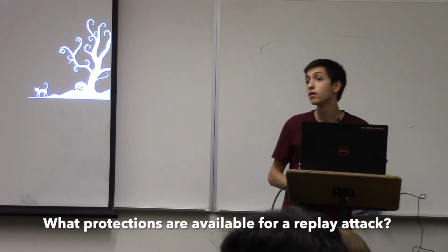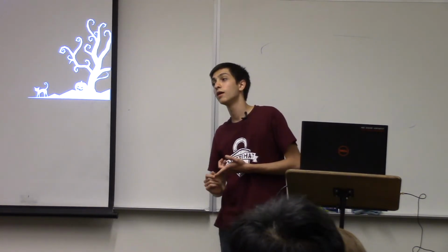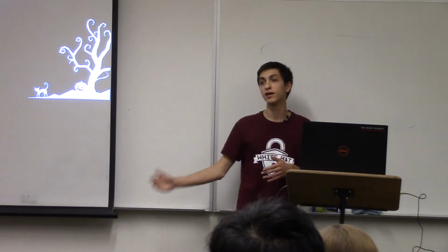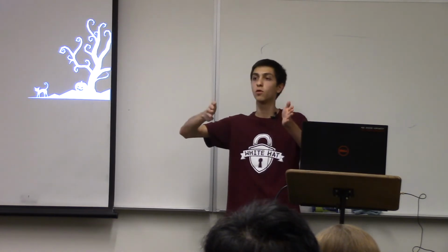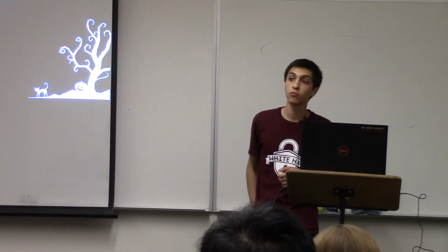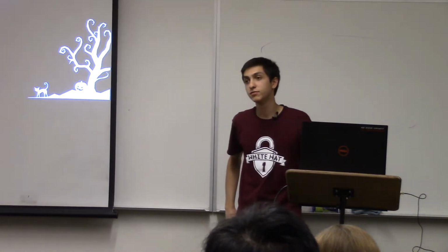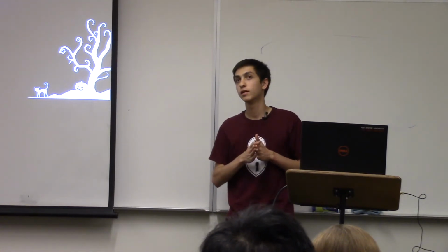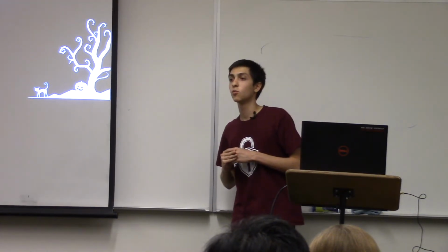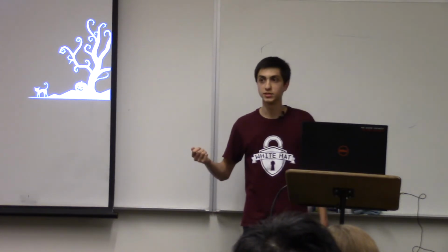Yeah? What protections are available for that replay attack? So you can do things where your code changes every time. You can use complicated math that does that. But there's also, if you change the code every use, well, what if I were to press the button out of range of the receiver? How would it know that I'm ahead now? Because I used a code, and you're going to increment that code. So you're going to increment the code every time you use it.